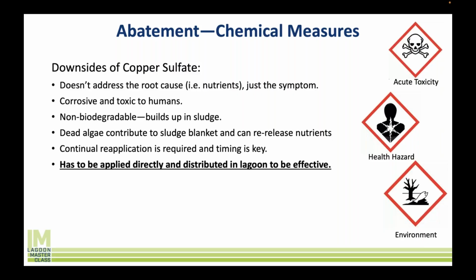Obviously, the analogy is a bit crude, but what I hear is you continually need more and more drugs to overcome and get the hit that you need, and the same thing will happen with your lagoon, right? You'll continually need more and more copper sulfate over time because you're just going to keep compounding, keep compounding, keep compounding. So this is not a solution. In my recommendation, this is not a long-term solution to an algae management problem. Okay, it's not. You shouldn't be using it for that.